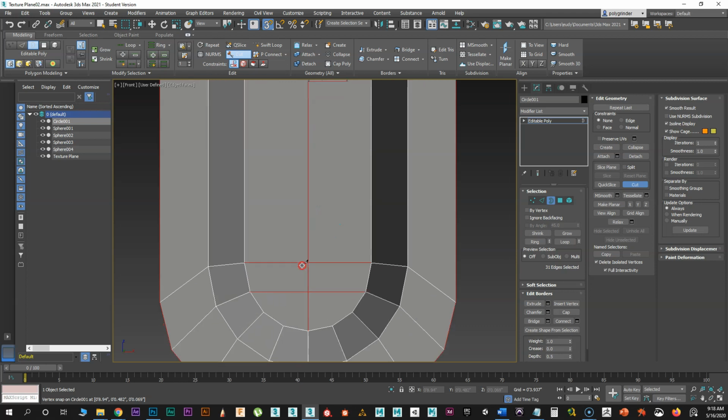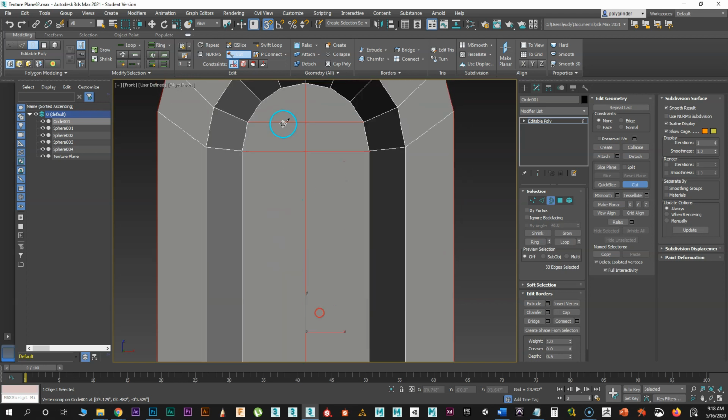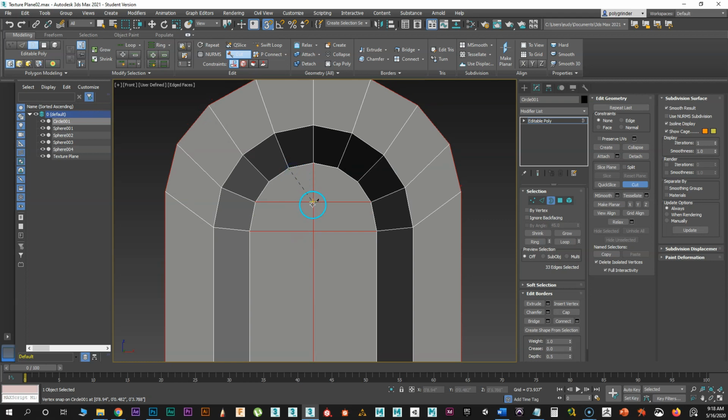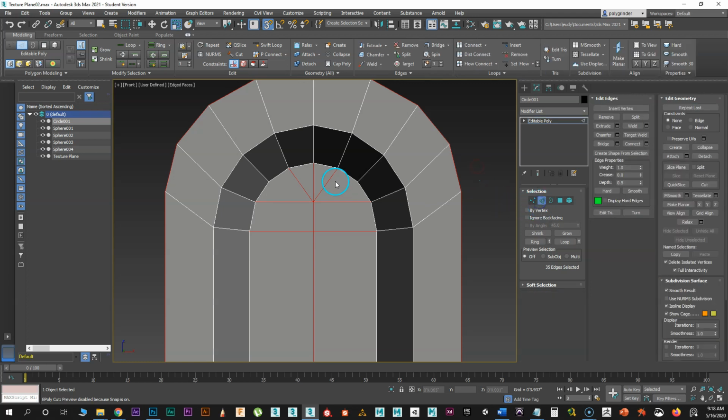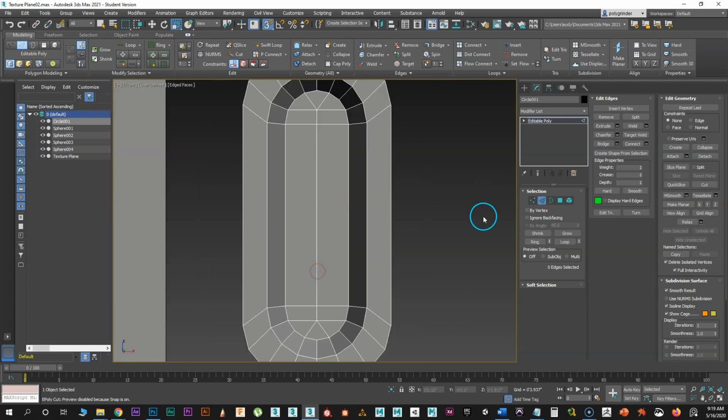And then we want to cut from here to there on both ends. Okay, then right click to get out of your cut. Then we want to go to this edge, highlight just one, and just click backspace. And we're doing that, so this is a quad, that's a quad, that's a quad. So here, backspace. So now this is all made up of quads.